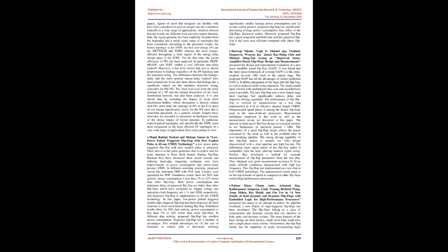Its latch structure is from the clock branch sharing flip-flop. Simulation results show that for 50% data activity, power consumption is 7% to 32% lower than other flip-flops. In different data activity, the proposed flip-flop has the smallest power consumption.